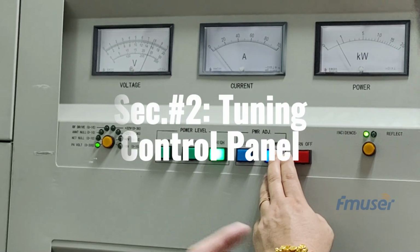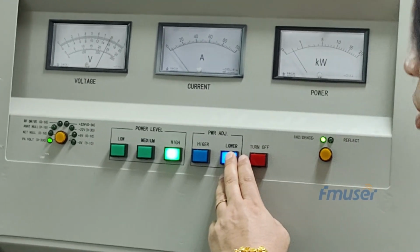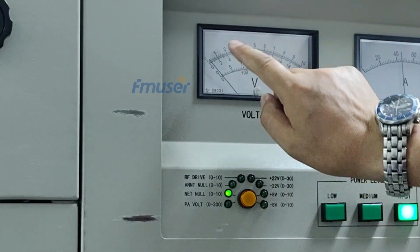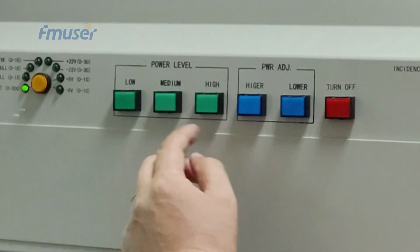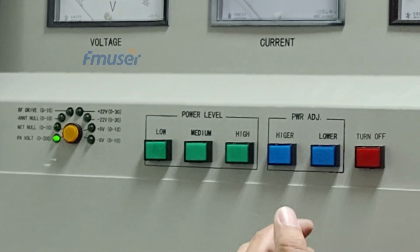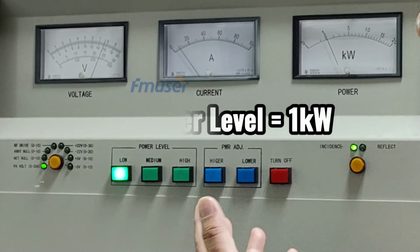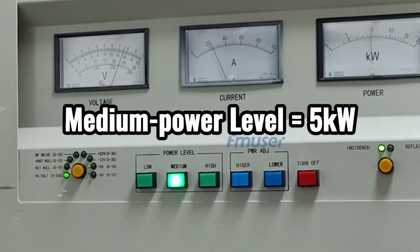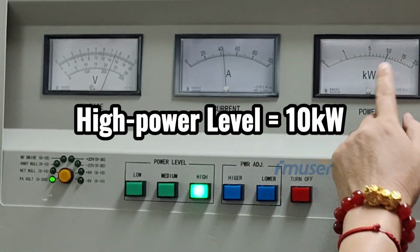The second section is the tuning control panel, consisting of 5 groups of buttons from left to right. The first group is the module shifting. This is the button group for shifting important built-in module voltages of the transmitter. The second group is the power level. This is the button group that controls the default power level of the transmitter, with 3 default modes. Low mode equivalent to 1 kW, medium mode equivalent to 5 kW, and high mode equivalent to 10 kW.